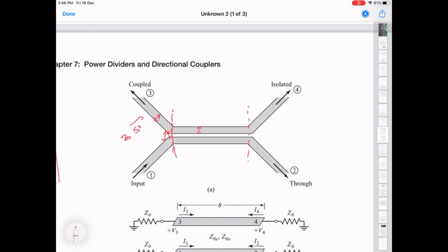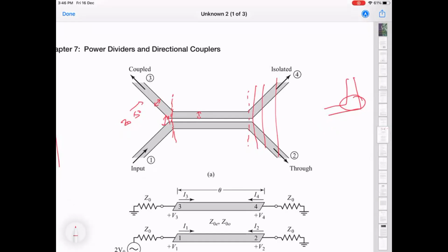In a design picture seen later, you will see that you can also make it perpendicular like this. But this edge effect can have some impact on the performance. In the analysis, of course, we do not consider that at all. There's no simple way of analyzing this, other than maybe breaking it up into several sections and calling them coupled transmission lines with different coupling, and then seeing how that affects the overall performance. So often these decisions have to be made with intuition, and these days with electromagnetic simulations, you can just fine-tune the geometry and see what gives you the best performance.